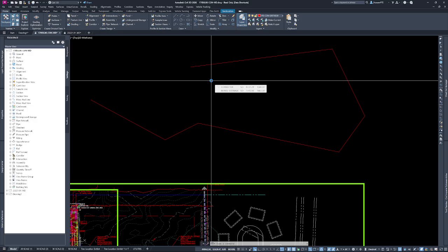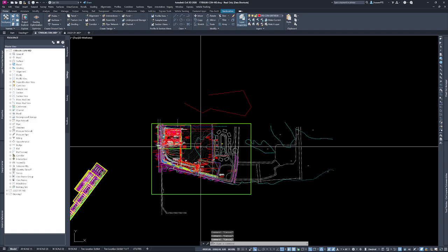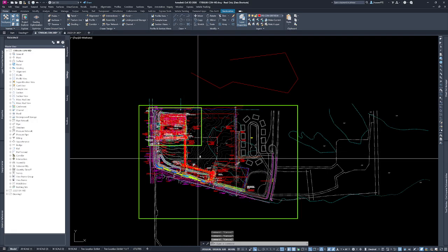And then one other thing I ran into recently that I'm still messing around with: one suggestion I make whenever we are working with files from outside of our office is do not block them into our files. If you need to, XREF them in and then trace over, or only get the information that you must have. That will help eliminate having all those RegApps loaded into your drawing and hidden in the background. And when you're done with the XREF, you can always unload or detach it, and that information is gone. It helps to minimize the number of layers in the layer manager.